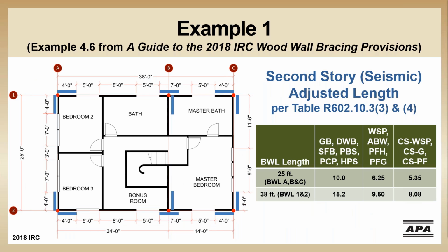So at the upper floor, these are the braced wall panels we had previously placed for wind. At 8 feet total for the lettered braced wall lines and 12-foot total for the numbered braced wall lines, we can stick with this layout for the methods in the last 2 columns on our table. To use a method in the first column, we would need a bit more length.